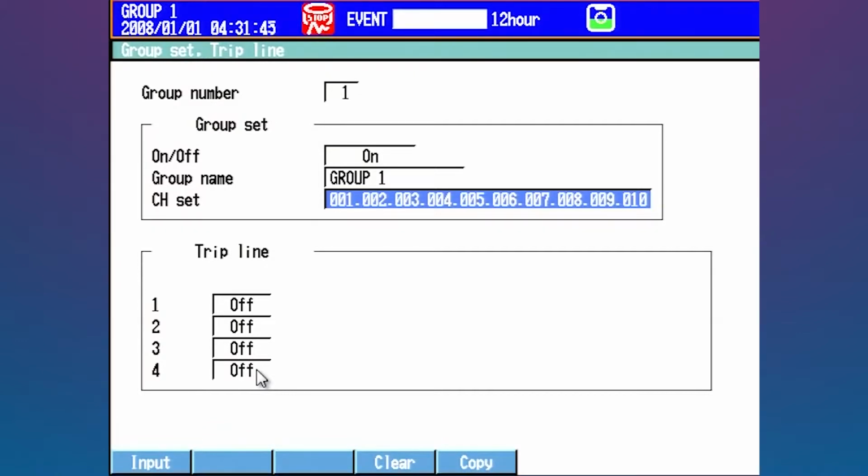So you can set this to be input channels, typically 1 through 48. You can use this for your math channels, which might be like 101 through say 160. Or you can also set this for your external channels. Alright? And essentially you can separate individual channels with periods, or you can do span of channels. Like you could go 1-10, and that would be channels 1-10. Plus you can mix and match your periods and your dashes.